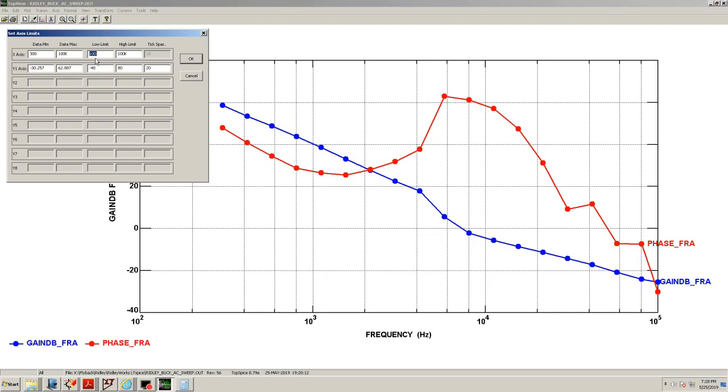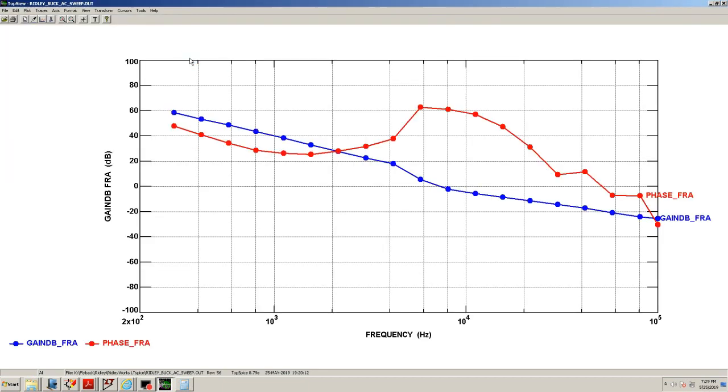So now we'll change this to low frequency since we started at 300, and be a little bit consistent with the Ridley plot. We'll set it there. Okay, so before I copy, I'll say that crossover is approximately here, the phase here.